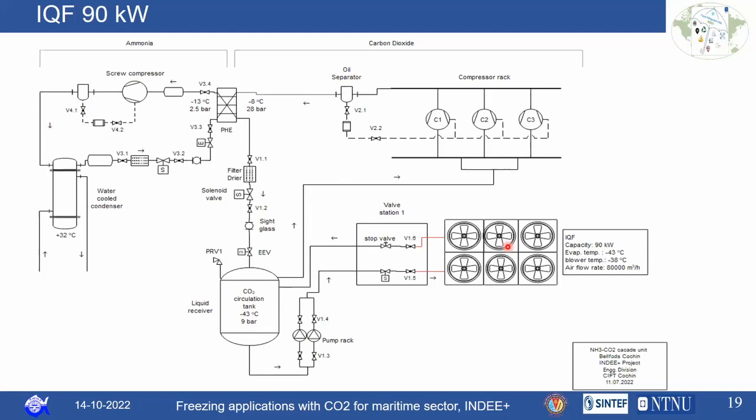Now, in the case of an IQF unit, you don't necessarily need a defrosting arrangement, because it is a continuous process. Unlike the blast freezer, which is a batch process where you need defrosting in between the batches, in an IQF unit you can carry out the freezing process continuously for a day, and at the end of the day you can just switch off the machine and it will naturally get defrosted. So we have proposed this system, or we are actually working on this system, for this IND plus project.